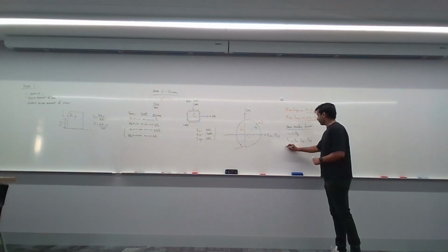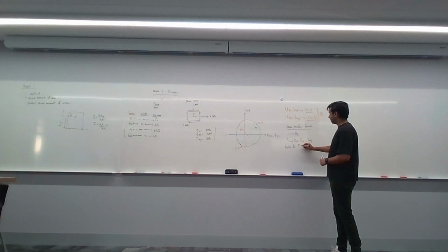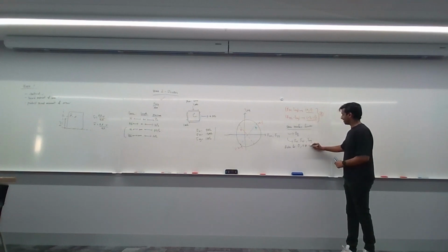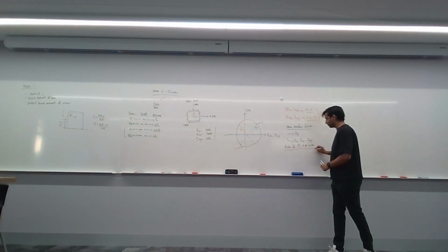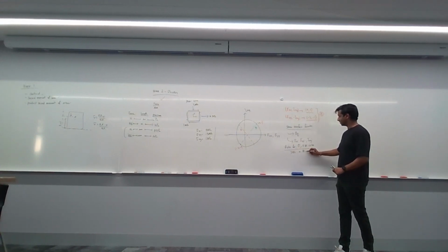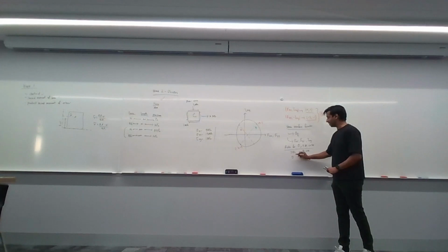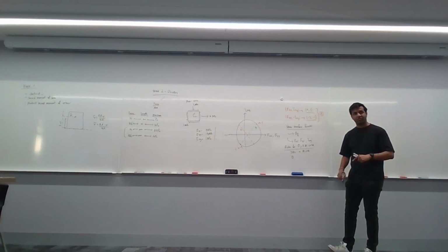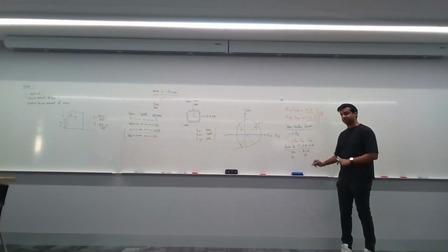Now, the rules for the stress and the strain Mohr circle, okay, they both have the same rules. Now you have your real life versus what's happening in the Mohr circle. If you rotate by an angle of theta in real life, you will rotate by an angle of 2 theta in the Mohr circle. That's true.